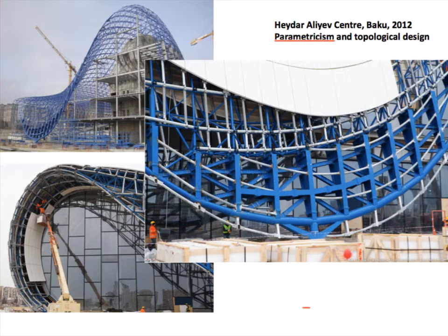Space frameworks are more efficient than solid slabs. Eye-shaped cross-sections are more efficient than solid rectangles. Tapered profiles are usually more efficient than parallel sides, and curvilinear forms more efficient than rectilinear ones. State-of-the-art methods of fabrication, such as 3D printing, can mitigate the difficulties of making complex forms to some extent, but do not eliminate them, and the machines and processes involved produce high carbon footprints.